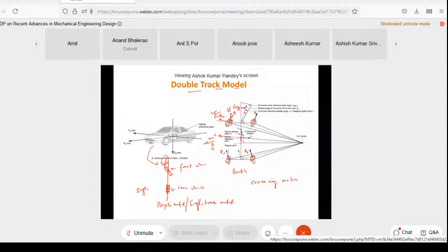Let us say your vehicle has the front axle here, and the rear axle here. If we call this B and this one L, then of course, if L is very much greater than B, you will see that this and this will act similarly. So we can say that I bring the equivalent effect over here and the equivalent effect over here, and try to analyze my vehicle only like a 1D effect, like a bicycle model. This is single track model. So long vehicles can be represented quite easily with the bicycle model or single track model, and that's how you will have to decide.